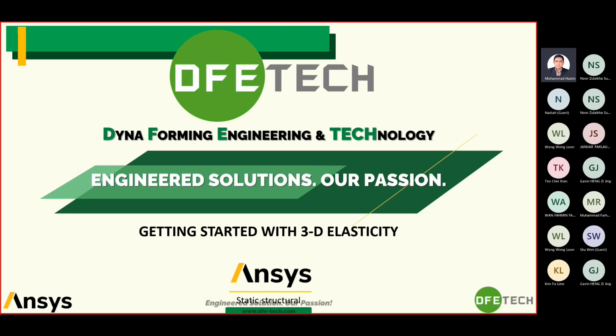For those who are not familiar with Ansys Static Structural, especially the newcomers, in general it is an analysis tool for static structural analysis to determine the displacement, stress, strain, and force in a structure or component caused by loads that do not induce significant inertia and damping effect. Steady loading and response conditions are assumed. That is, the load and the structure response are assumed to vary very slowly with respect to time.